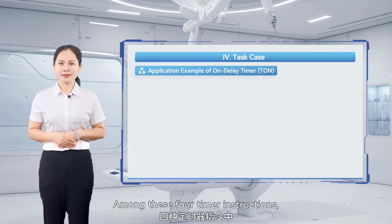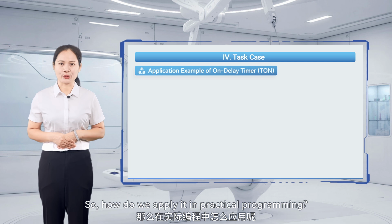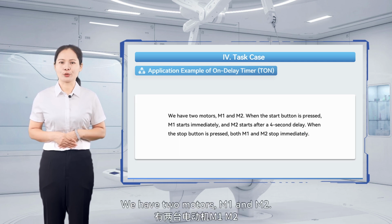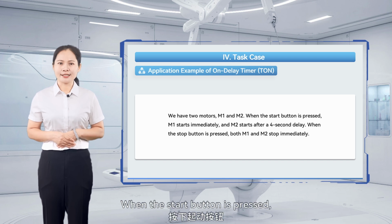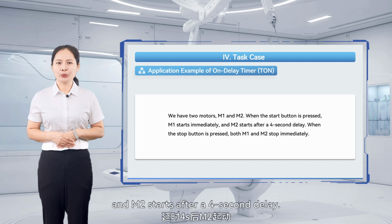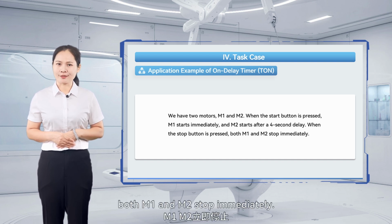Among these 4 timer instructions, the on-delay timer, TON, is the most widely used. So, how do we apply it in practical programming? Let's work on an exercise. We have 2 motors, M1 and M2. When the start button is pressed, M1 starts immediately, and M2 starts after a 4-second delay. When the stop button is pressed, both M1 and M2 stop immediately.